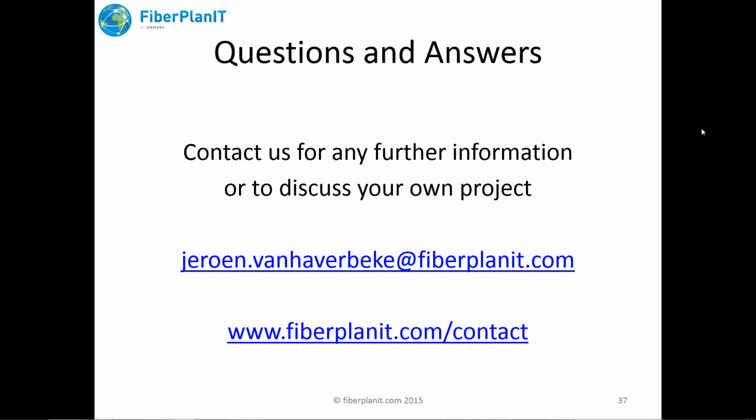So in the demo that I gave, we had the building polygons and home point locations, the address points, and there were multiple address points in the building. We gathered these into one single demand point. So a multi-dwelling unit is represented by one single access point to the building, and the number of fiber connections that is required is also consolidated into this point.